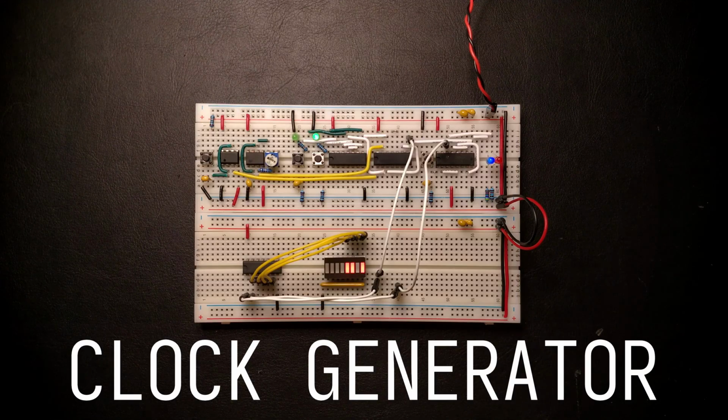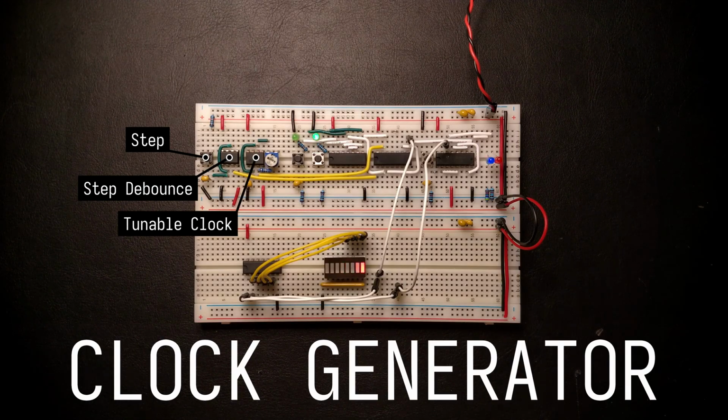It has a bunch of pretty useful features. On the far left, there's the step button, which generates a single clock pulse, which will be handy for debugging circuits. To make this work, we had to use a 555 timer chip and a filter capacitor to get rid of the unwanted bounce in the button's metal contacts. There's also a free running clock, implemented again with a 555 timer chip, where we can use this variable resistor to dial in the clock speed we want the CPU to run at.